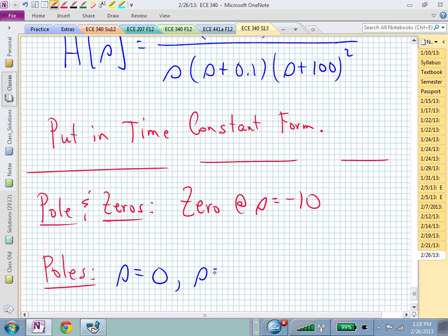That will cause the denominator to vanish. We have another root of the denominator, which is a pole. One of our poles is at the origin. We have another pole at minus 1/10. That's pretty close to the origin, isn't it, relative to these other 2.